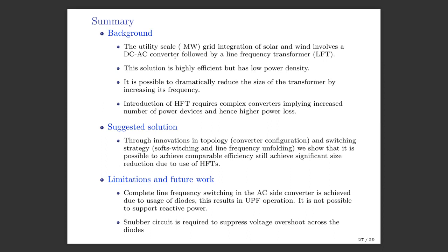And we know that phase shifted full bridge has this problem of voltage overshoot in the secondary because of the parasitic capacitances which are present in the diodes, and which causes ringing and all that. And you need active snubber circuitry there. Now, we are also working on this, a few of my students are working on this, to find a solution that can solve this age-old problem.